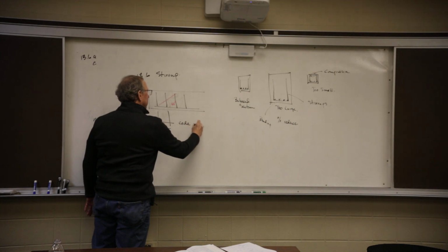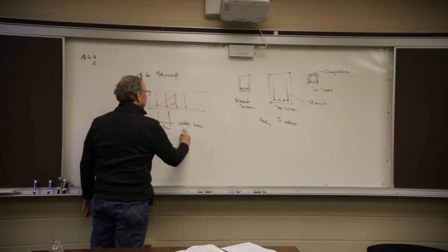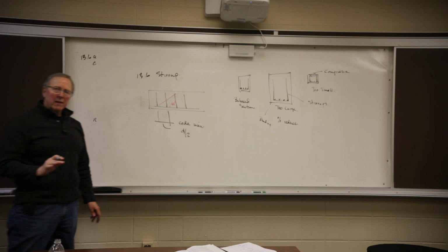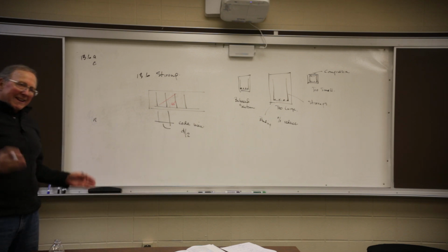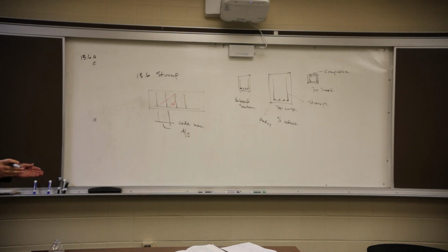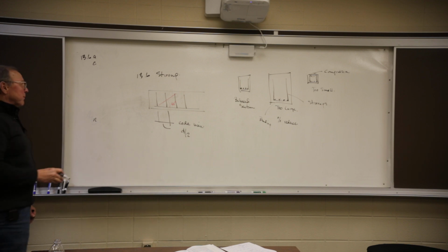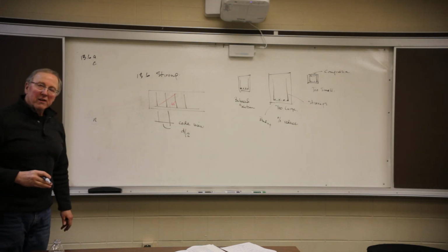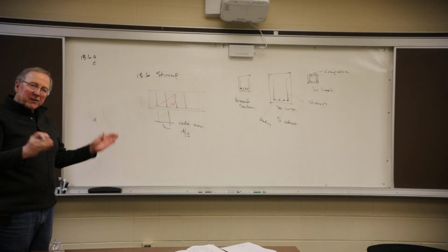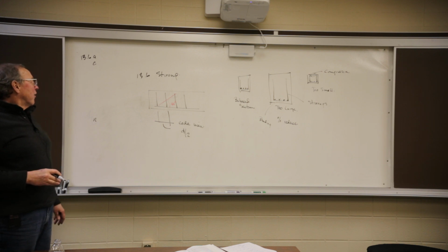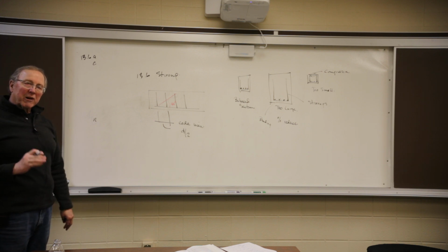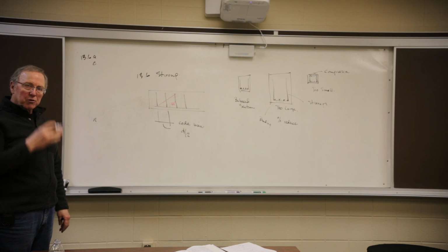And code minimum is the effective depth divided by 2. So if I've got an 18-inch effective depth, the farthest the stirrups could be placed apart is 9 inches. It's a 20-inch effective depth, 10 inches. Okay, the only thing that will trump that is if structurally we require them to be closer.